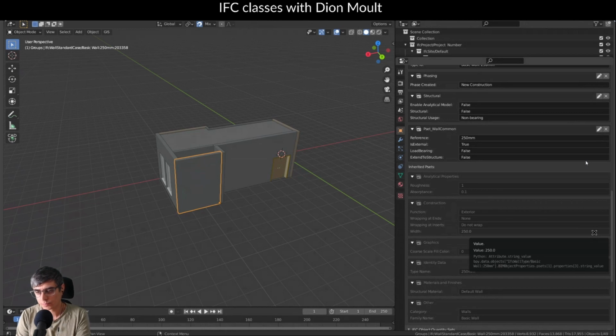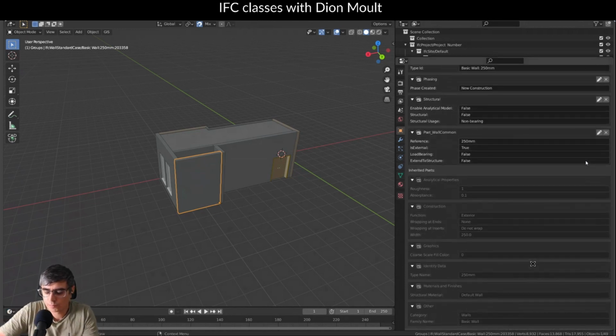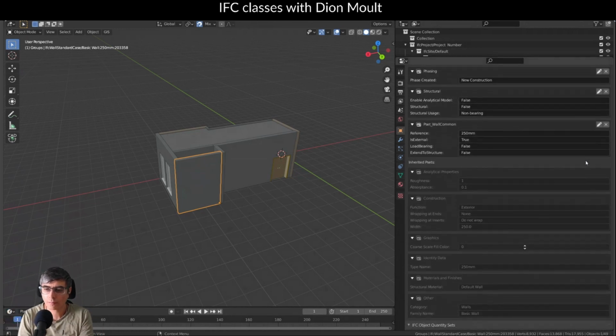There's a slight edge case which some people in the audience might be picking up now about user-defined and predefined type attributes, but for most things, you can assign properties to the type, and it's actually recommended to do so, especially if it's valid. Well, of course it's recommended to do so if it's valid. You should do it, and that will save you from creating a whole bunch of unnecessarily duplicated data.